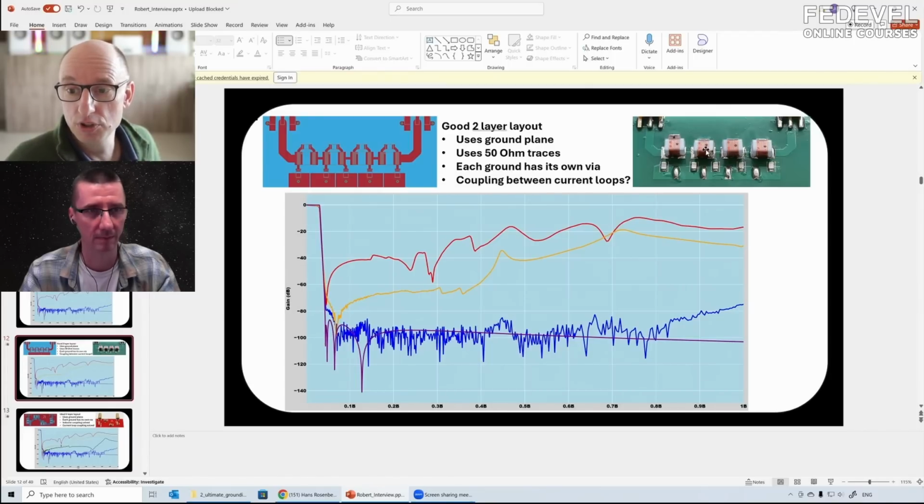But you only need a lousy transformer to completely ruin a 100 dB suppression filter, because that's a factor of 100,000. If you have minus 60 dB of coupling, which is already a very good number, you're completely screwing your filter performance. But when I was investigating this, I found something else.